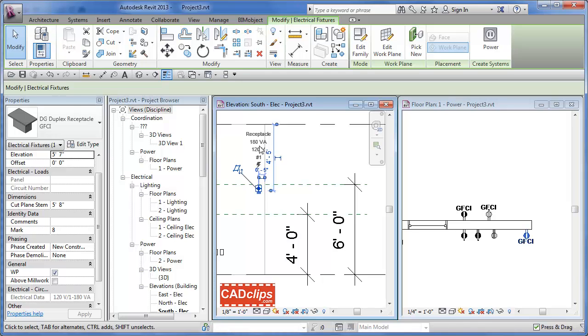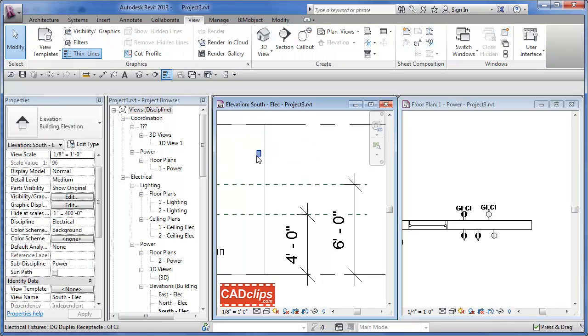There it is. So now the challenge is, what if, and I'm using a shift click, what if this guy is up here, way up here, and this does have to be here, and I want it to show? What we have to do is add an imaginary model line, an invisible model line in here that sticks down like a stem, and as long as that imaginary line sits within here, all of a sudden it'll show up. It'll never show anywhere because it'll be invisible, but it will get captured by the view range and therefore show up.